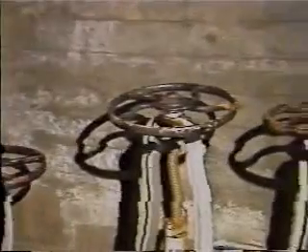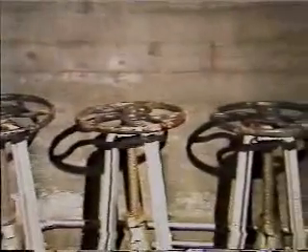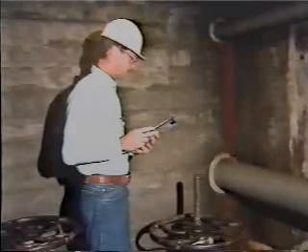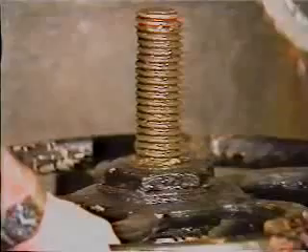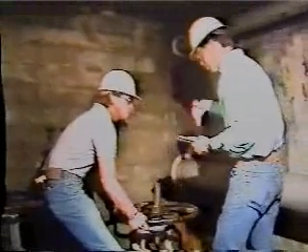Gate valves are widely used. They develop many of the same problems that slide gates do. The valve may suffer from cavitation, corrosion, leakage, cracking, and broken or missing parts. If the valve can't be reached for a visual inspection, the only way to tell if it's working properly may be to watch for sticking and roughness when the valve is opened and closed.